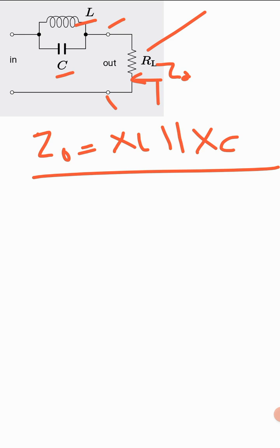So if you do the analysis and calculate the voltage gain VO or VL divided by V in, how it varies with respect to frequency, and impedances ZO and Z in, how they vary with respect to frequency, you can understand and know the frequency response of this circuit, and you can see what kind of filter it is acting as, whether it's a low pass filter or high pass filter and so on.